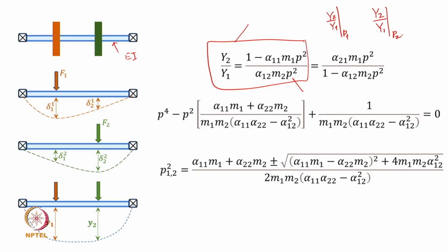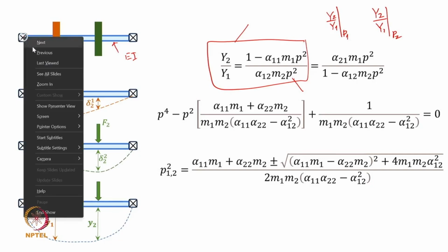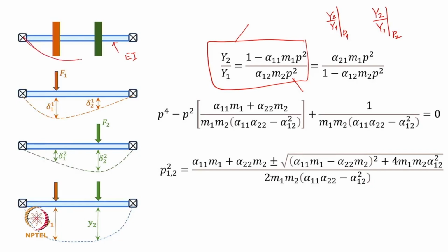Okay. And with that you get an appropriate mode shape, and although you can find this out by appropriate numeric values, it so turns out that the first mode will show the mode shape to be this, which is expected, right. So, both the disks are going to move in the same direction, whereas in the second mode this disk can have this peak value and this disk will have this peak value, and so on.